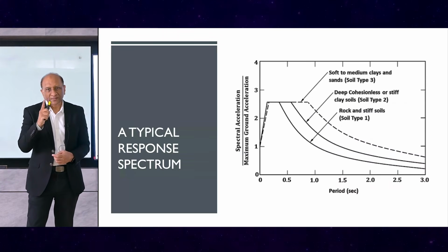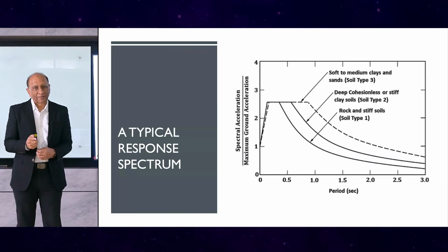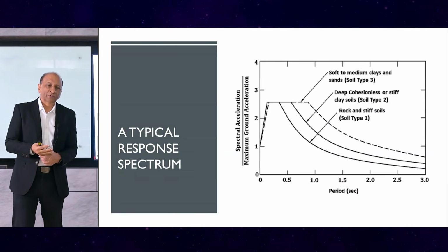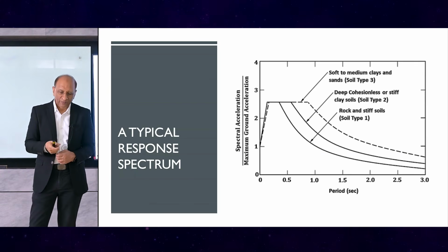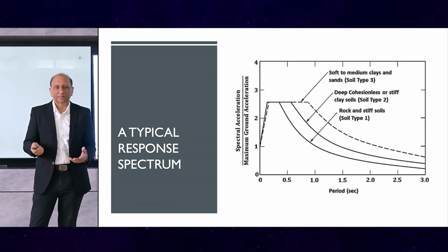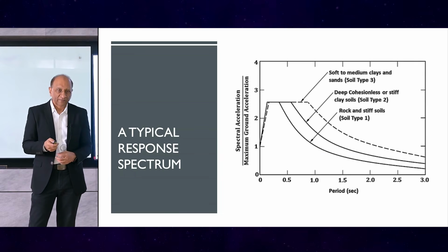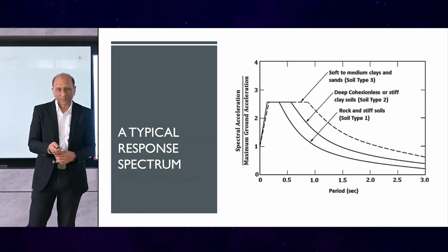And response spectrum is affected by the type of soil, because the ground motion from the rock coming all the way to the structure is heavily influenced by that. And in Bangkok, the recent earthquake has shown that this is a very important magnification that we have to consider.